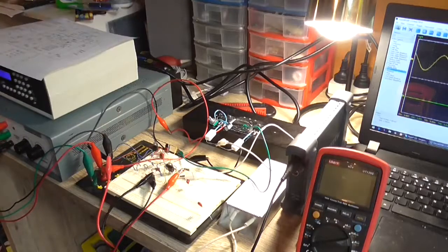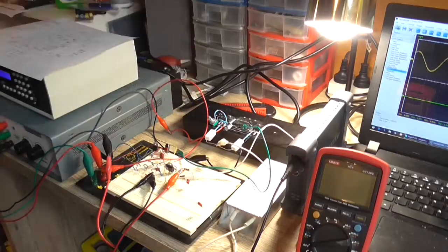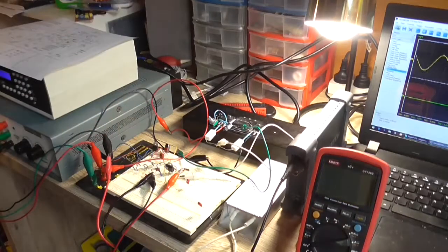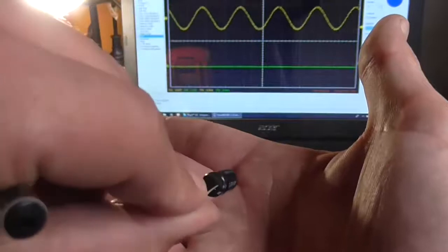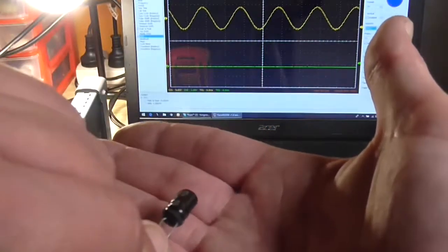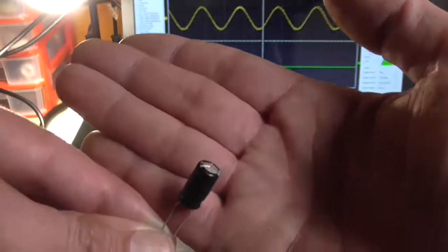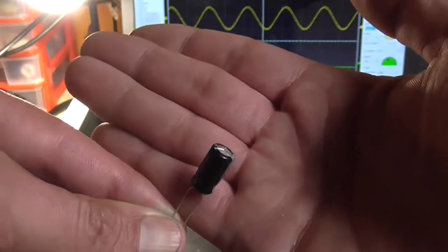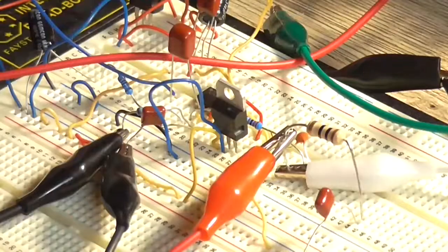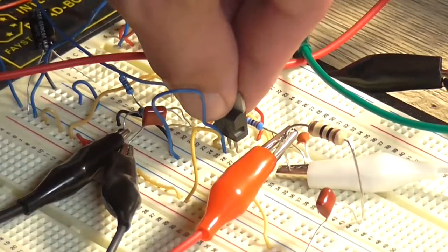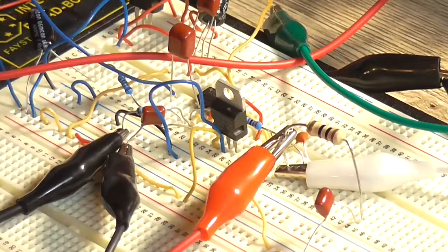Now I also had a 100 microfarad bulk filter capacitor across this negative regulator, and it was getting hot, the regulator that is. I couldn't figure out why, and that's because I connected it backwards, reverse polarity, and I basically just blew the capacitor. It didn't go bang or anything, wasn't spectacular. You can see, maybe or not, that it's starting to bulge there. I had it backwards, that was red hot, it blew, and that was the end of that. Not that it's needed in the circuit anyway, but that's the reason why this negative regulator was getting hot. Now it's mildly warm. But yeah, always check polarity on capacitors.